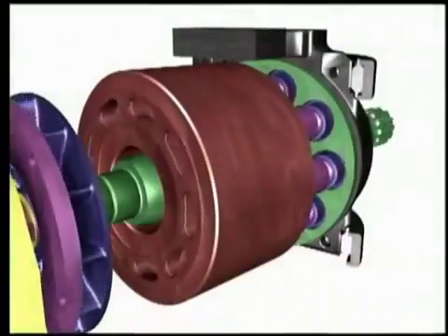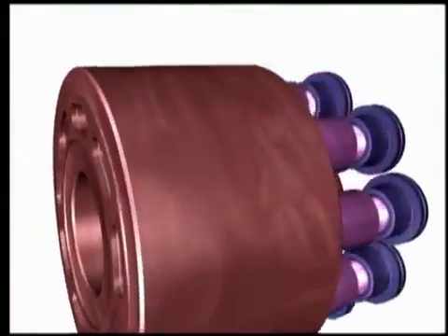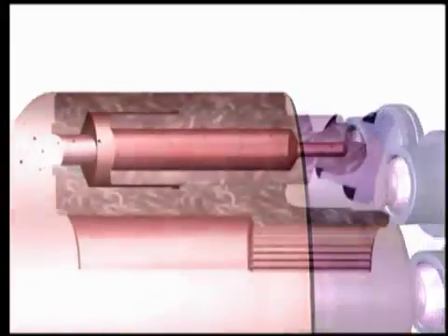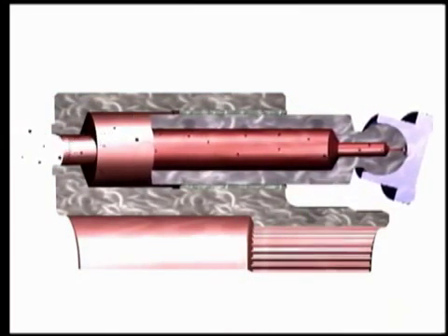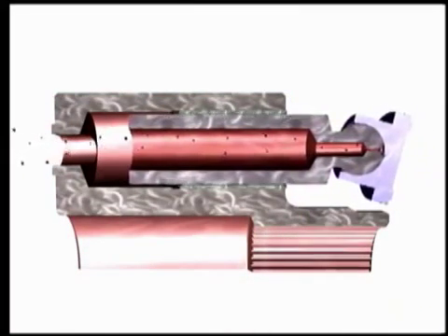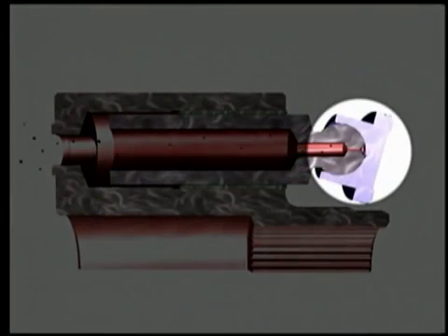Notice how the contaminants break down the edges of the port plate. As we look at other ways contamination can cause problems, we turn the animation of the pump 90 degrees onto its side. Particles can lodge between the piston and the brass slipper foot, seen in purple, causing it to jam. Or the contaminants can scrape walls between the barrel and piston.